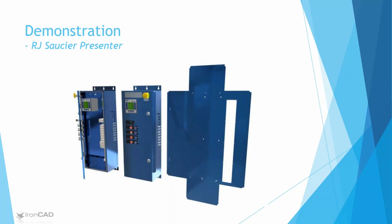And just keep in mind, if you don't use the bulk creation tool all the time, you don't necessarily have to use that front view direction, but it is quite handy, especially when you get into different orientations of your model. If your models are rotated in 3D space and weird orientations, that front view definition really eliminates any issues when you go and create your drawings. You can quickly pick your part, it'll be oriented right, and you can create your view layout. So it is a very handy tool, but not always necessary to use if you don't like.